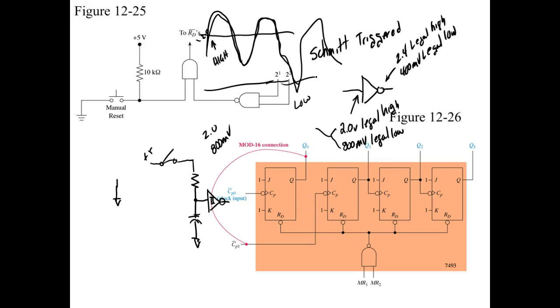So the advantage of a Schmitt trigger, we use this a lot on stuff that we're getting from the outside world, because there's so much noise in the outside world, right? You understand? That might generate a pulse that would get it into the illegal level.